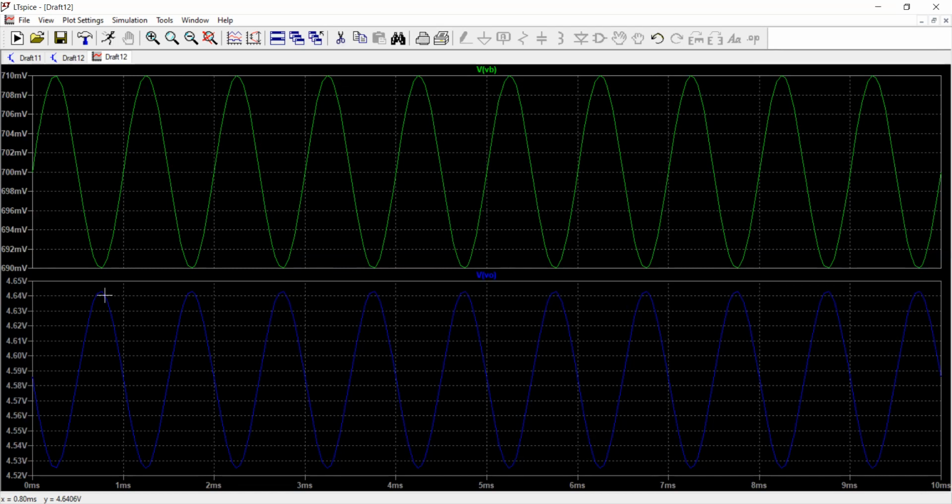So about 6.5 times the gain. And theoretically, we calculated about 10 times, right? So there is this difference, but you see the phase is inverted. You have positive and negative here. The output is also inverted because that's the common emitter mode, a 180-degree phase shift.